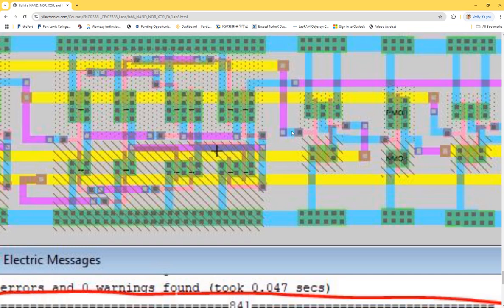There's no via called via 1, 2. Via 1 shorts it to metal 1, via 2 shorts it to metal 2. There's nothing that can drill a hole throughout the whole chip, right? It doesn't exist. So drill a hole first to metal 1, then drill another hole to metal 2. That's how that works. You can imagine the shape in the 3D structure in your mind. Okay? Make sense?